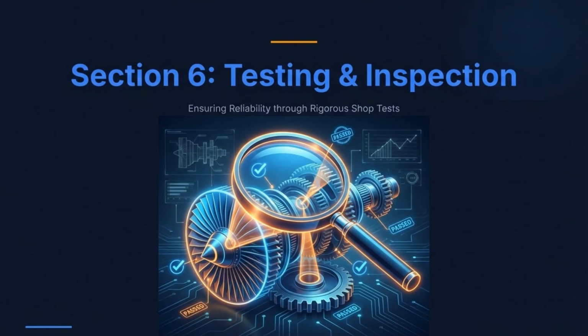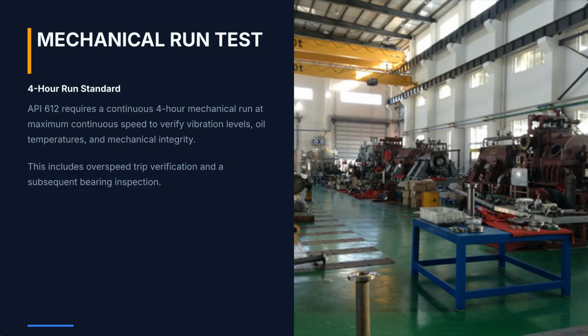We will proceed now to the testing and inspection section to ensure reliability through test procedures. Reliability is proven in the shop. While API 611 is okay with a 1 hour run, API 612 mandates a continuous 4 hour mechanical run at maximum continuous speed.